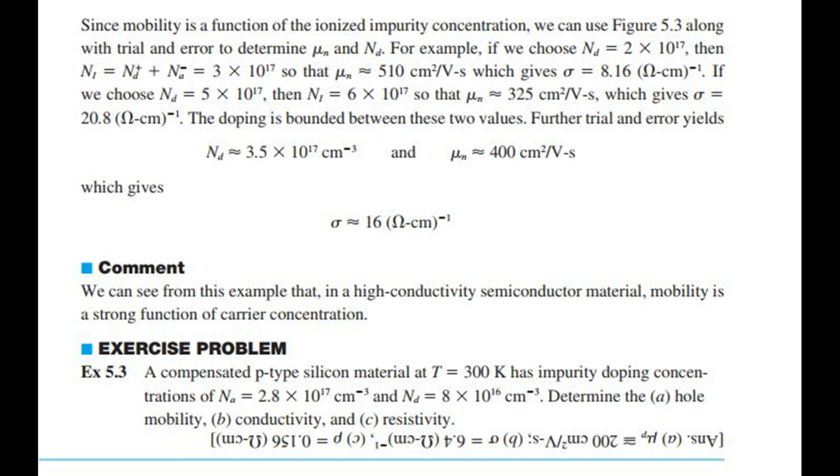Further trial and error yields N_d equals 3.5 times 10^17 per cubic centimeter, and mu equals 400 square centimeters per volt-second, which gives sigma equals 16 (ohm-centimeter) inverse. Comment: we can see from this example that, in a high conductivity semiconductor material, mobility is a strong function of carrier concentration.